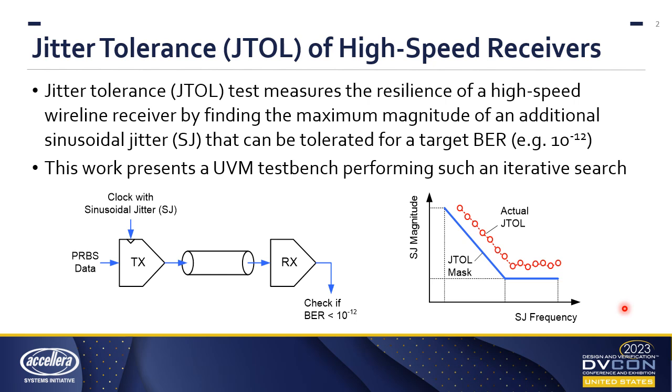This work presents a UVM test bench for measuring the jitter tolerance. To do so, the test bench must be able to simulate analog circuits in SystemVerilog and perform an iterative search, finding the largest sinusoidal jitter magnitude in a small number of trials.